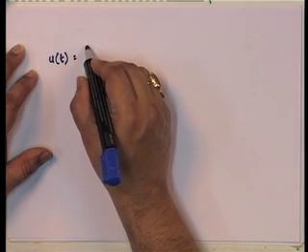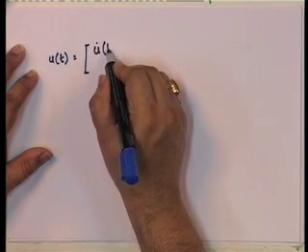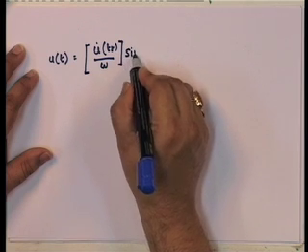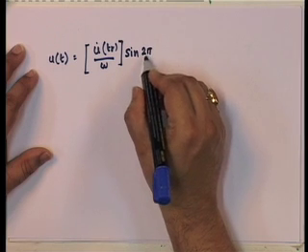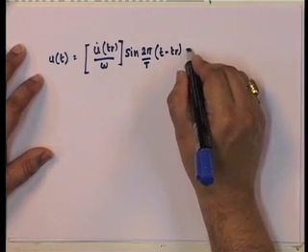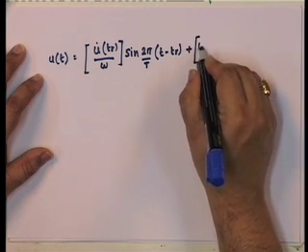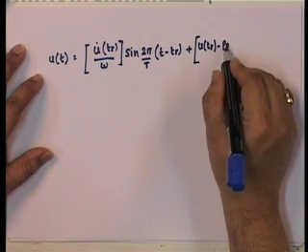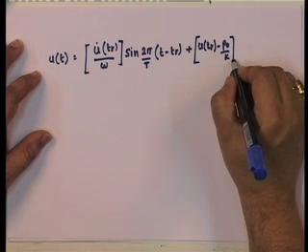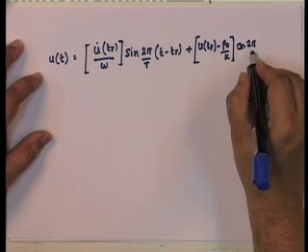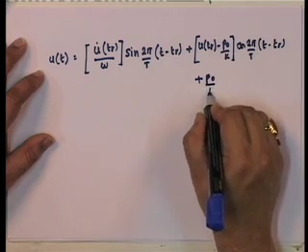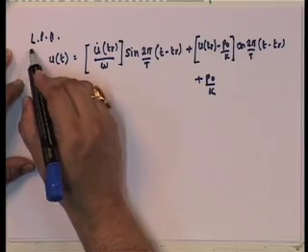So, this is going to be u dot(t_r) upon omega into sine of 2 pi by T into t minus t_r, plus u(t_r) minus p naught upon k, cosine of 2 pi (t minus t_r) upon T, and plus p naught upon k. So, this is load phase 2 u of t.